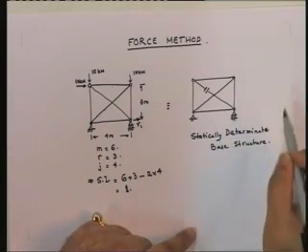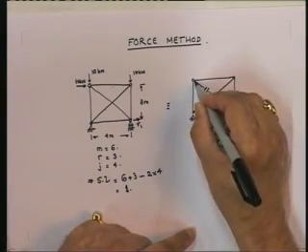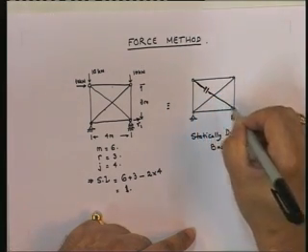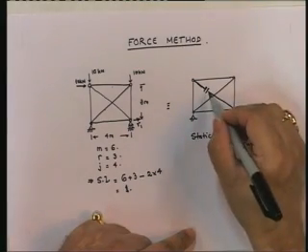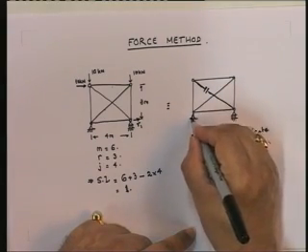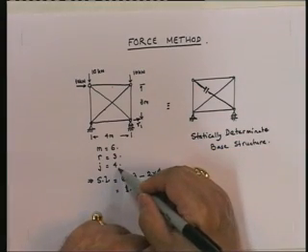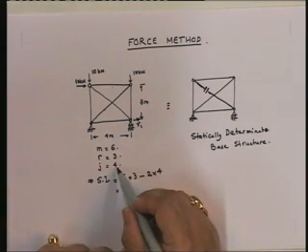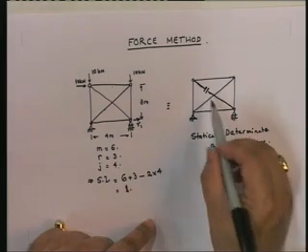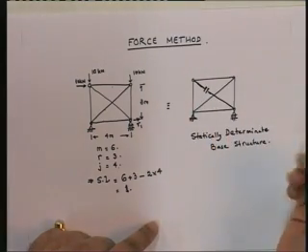if you look at it, suppose in this particular case, what have we done? We have cut this member. Once we cut this member, what happens? We know that the force in that member is 0. And since we know the force in the member is 0, let's look at it. Now how many equations of equilibrium do we have? We still have the same number of joints. So the number of equilibrium equations are still going to be 2 into 4. Okay. Only thing now is the number of members has been reduced by 1, because one of the members we know is going to have 0 force. So it becomes a statically determinate structure.